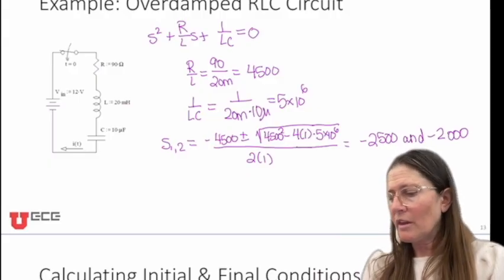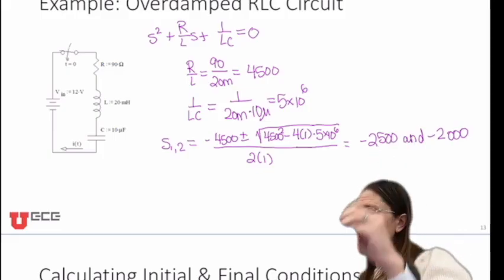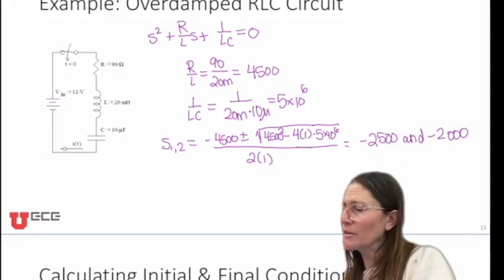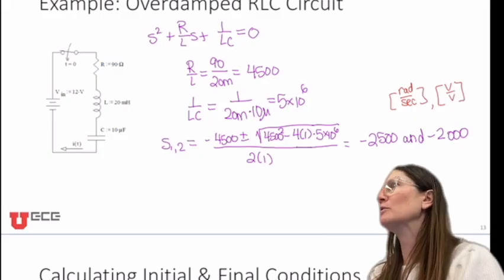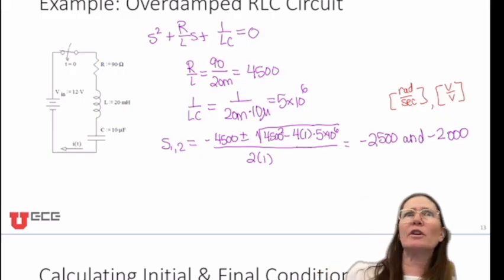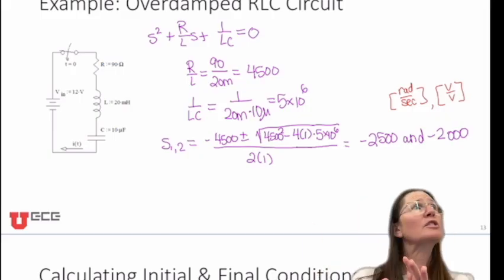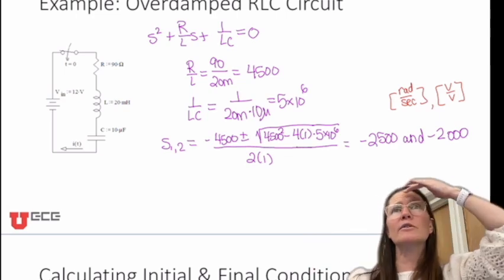So these numbers from a circuit are going to have default units of radians per second. And remember that the default unit was volts per volt of magnitude. So this goes back to those Bode plots, where when you find the transfer function, your units there will be volts over volts, and then these values of roots are going to be radians per second.